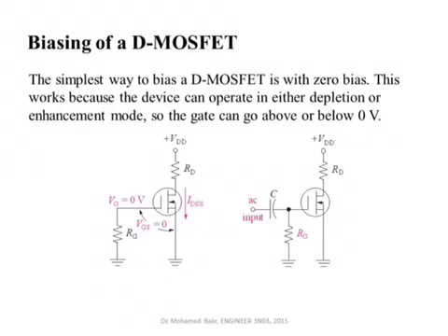Here there are a number of types of biasing. I'm showing here only one type, which is to connect the gate to ground through a resistor. This is also a self-biasing approach. You can bias it through many other techniques, and here I'm showing you can apply your signal here, for amplification, and of course your output can be collected from here from the drain. So you get an amplified signal of the weak signal applied at the input. And there are so many other biasing circuits, but we'll just focus on one or two of them.